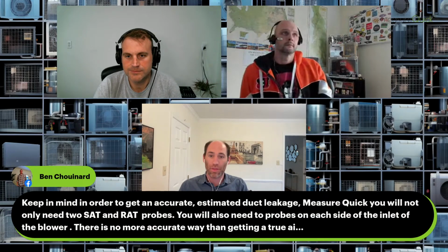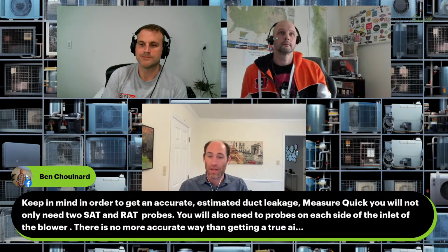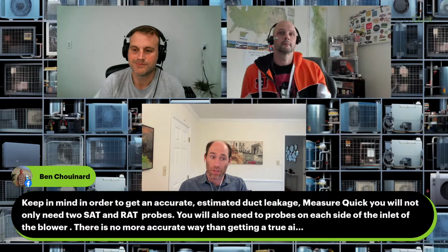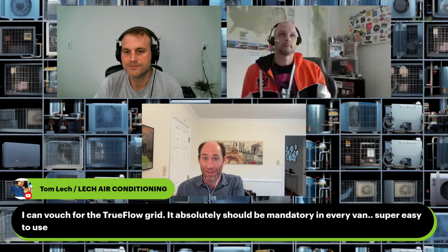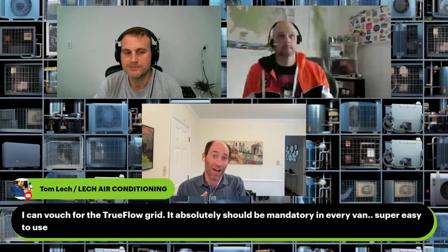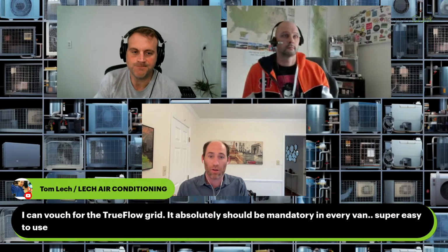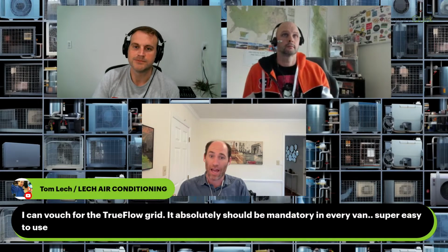So just be careful with the passive airflow hoods, and if at all possible, I know they're expensive, but invest in good tools. If you're going to do room by room airflow balancing, and you want to do that to plus or minus 5% or 10%, you need a tool that has better accuracy than that, or you're going to be very frustrated or confident in something that is not right. So if you can, use a powered flow hood. It's got a fan in it that compensates for any pressure that it adds to the measurement and gives you very accurate and repeatable results.